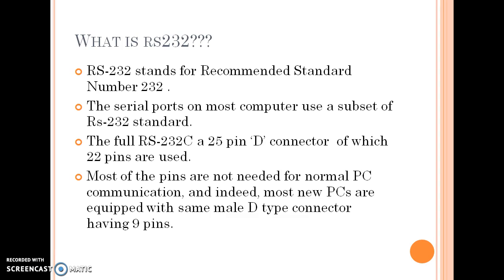Now we see what is RS-232. RS-232 stands for Recommended Standard Number 232. The serial ports on the computer use a subset of RS-232 standards. A full RS-232C has a 25-pin D-type connector, of which 22 pins are used.